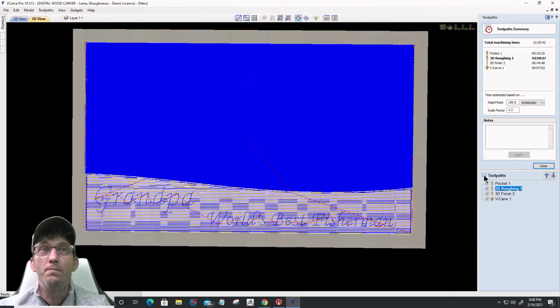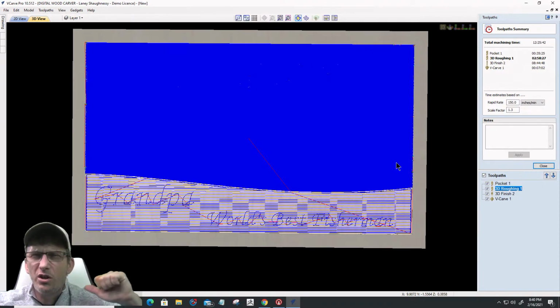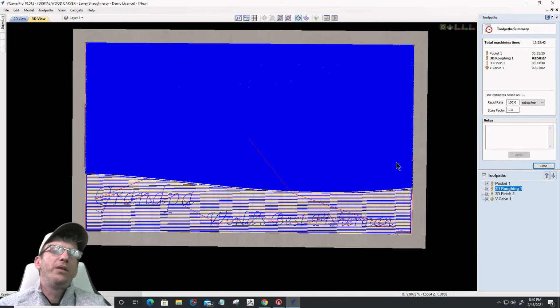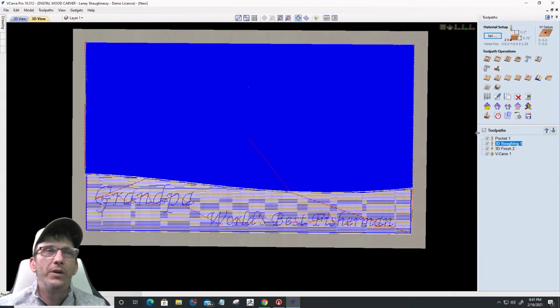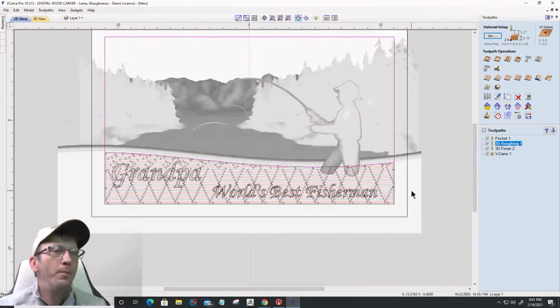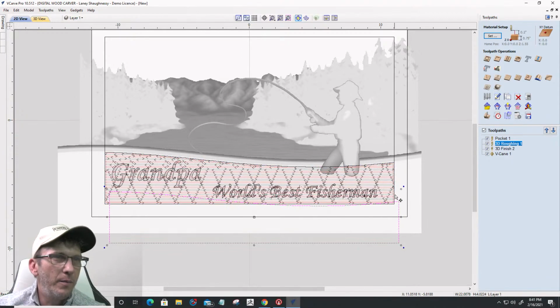So all together on this job, for me and my toolpath speeds and feeds, if you're on a big commercial machine, you can run hundreds of inches a minute, right? You know, and things like that. On mine, can't, right? I have a 2440 that has a rapid rate of 150 inches a minute and stuff. So we are at a total runtime of about 12 hours versus, if we went back, and let me find my, let me move this out of the way for a minute.